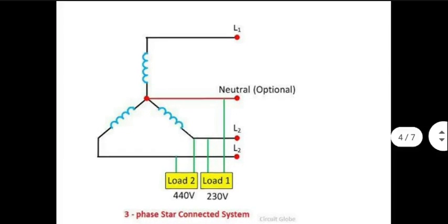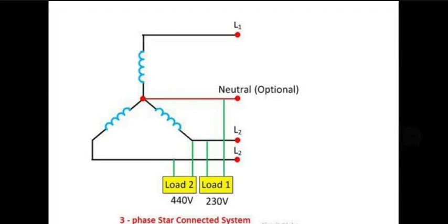These are not inductors, by the way. Generators typically have inductive behavior. That means their input impedance is highly inductive. That is why instead of drawing signal generators in the diagram, they have shown inductances. These are not passive things. These are actually generators in the 3 arms of the star connection.